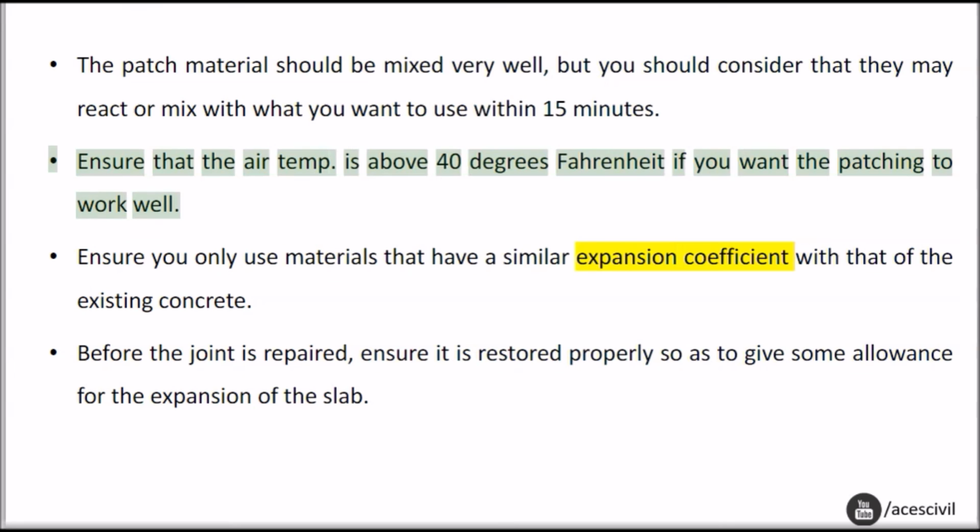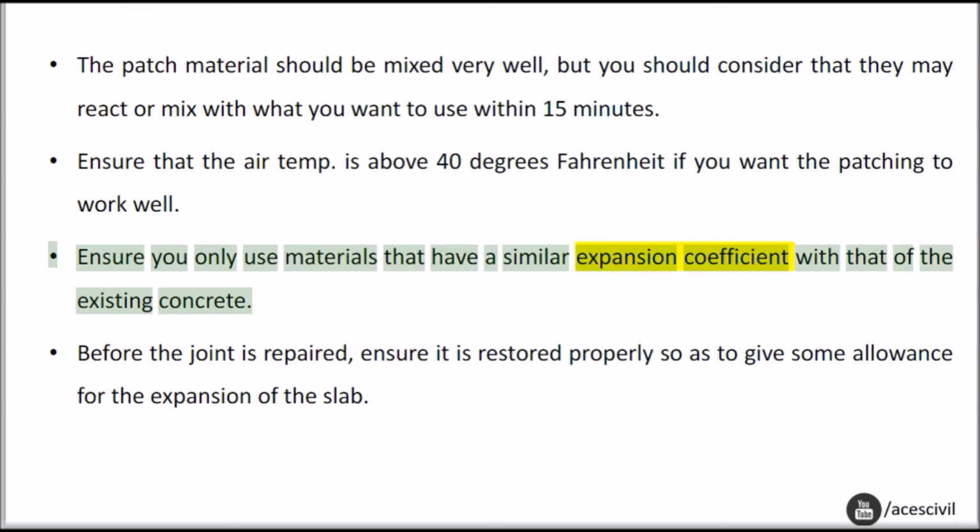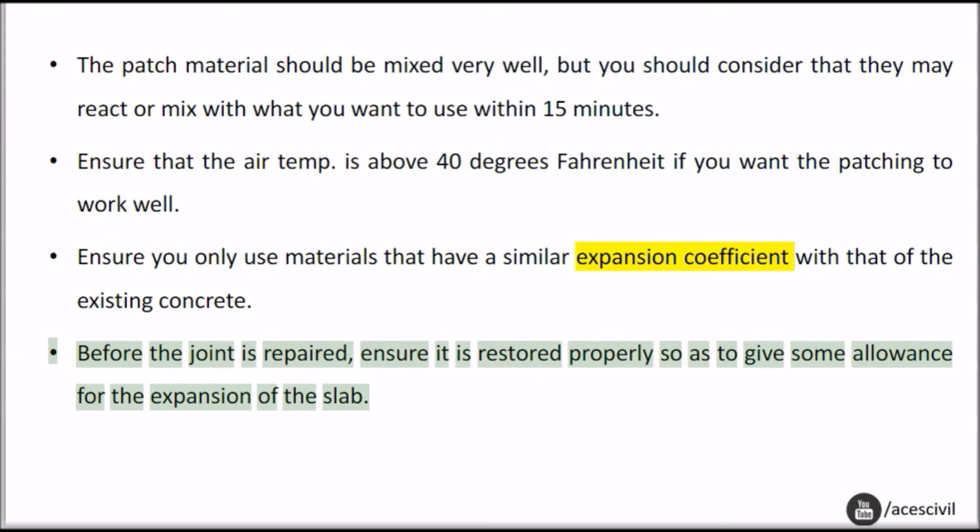Ensure that the air temperature is above 40 degrees Fahrenheit if you want the patching to work well. Ensure you only use materials that have a similar expansion coefficient to that of the existing concrete. Before the joint is repaired, ensure it is restored properly so as to give some allowance for the expansion of the slab.